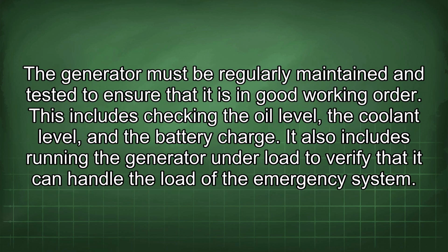The generator must be regularly maintained and tested to ensure that it is in good working order. This includes checking the oil level, the coolant level, and the battery charge. It also includes running the generator under load to verify that it can handle the load of the emergency system.